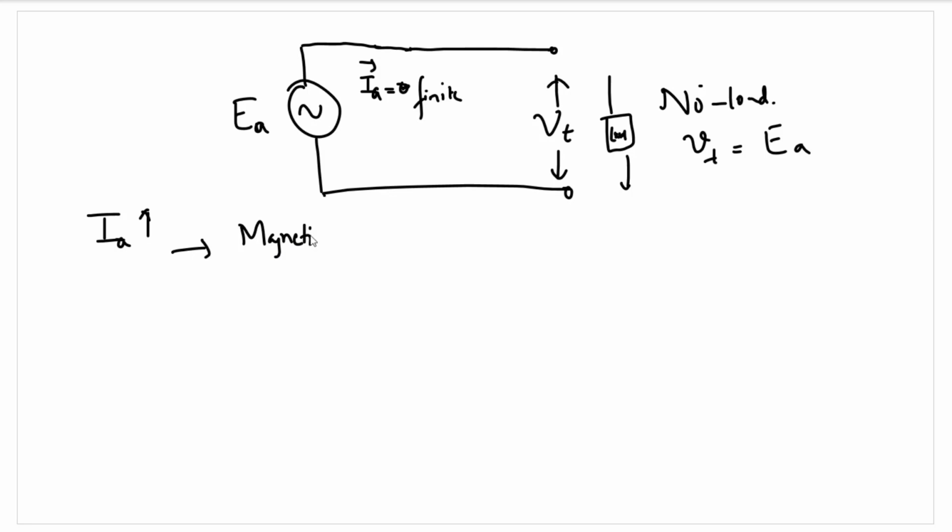The DC was producing a magnetic field, that was the rotor magnetic field. Now, the current flowing in the armature, because of the loaded nature of the synchronous generator, will result in the production of its own magnetic field, that is the stator magnetic field.